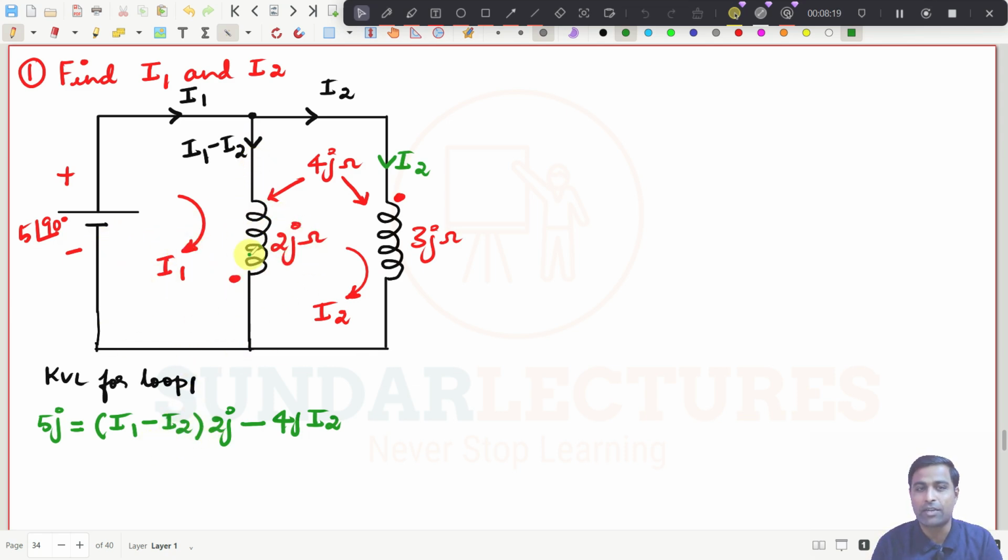I have told you already. You don't put minus for the self-induced EMF. I have just taken this current and the 2j, that is this coil's reactance, and I have directly put this value. And I have to see what happens to current in both coils to write the mutually induced EMF. This current is leaving the dot, this current is entering the dot. So the minus will come here, and this value is 4j, and what is the current flowing in the second coil? It is I2. Then I can write like this.